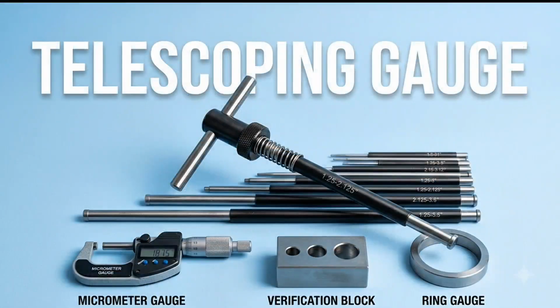A telescoping gauge measures the internal diameter of deep holes and cylinders. The spring-loaded measuring ends expand inside the opening, locking into position before being measured with a micrometer. This method provides accurate measurements for parts that cannot be measured directly.